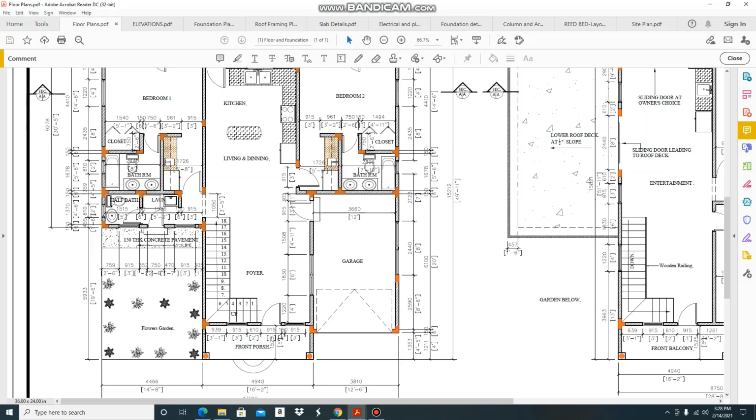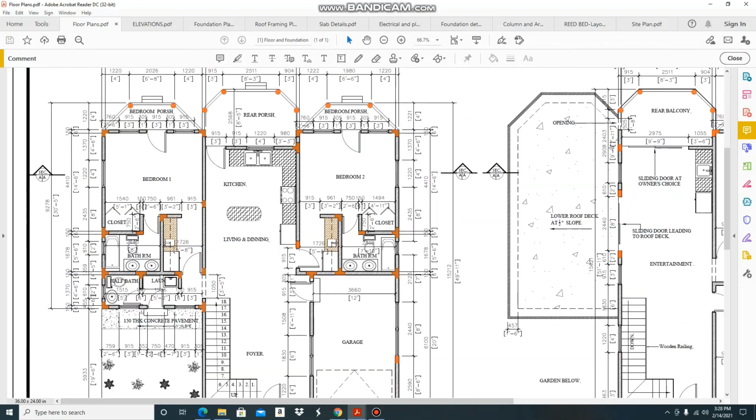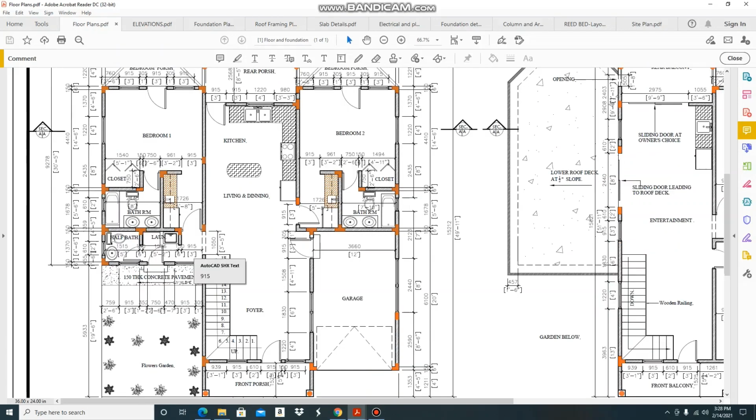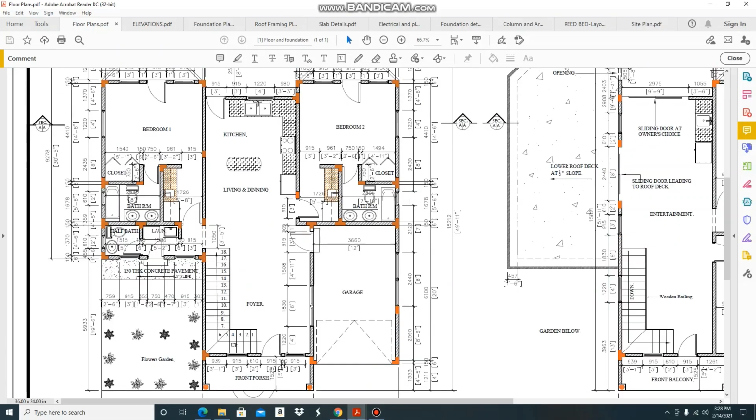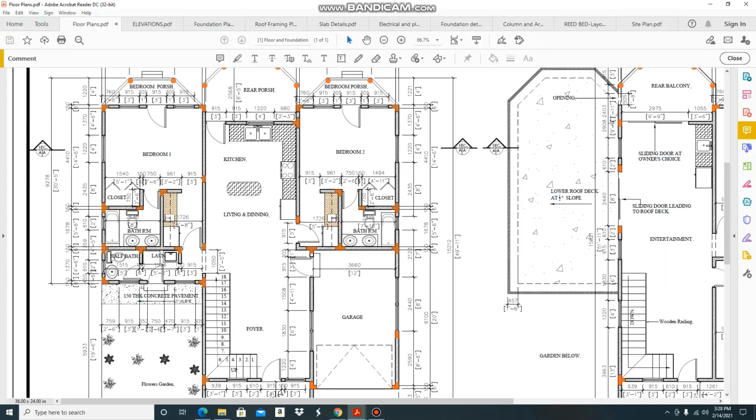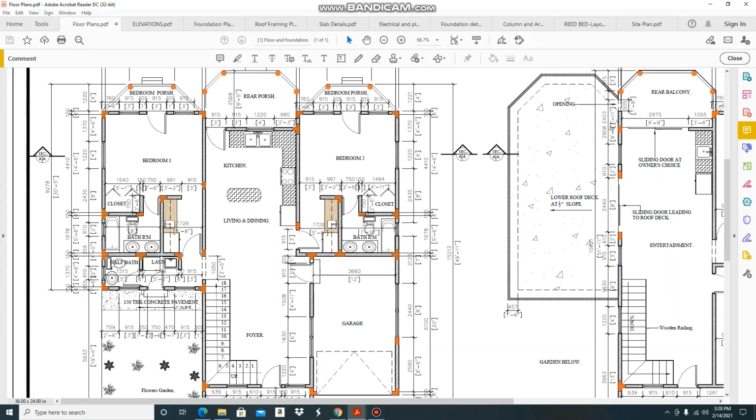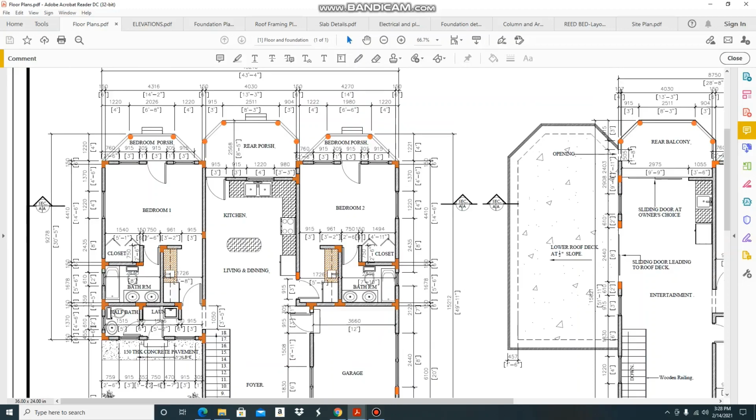And you just pretty much draw what you see. So always take that into consideration that your floor plan is cut 4 feet above your finished floor level. And my word to you, if you're a builder or a contractor.